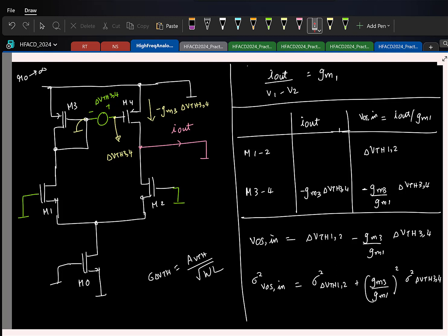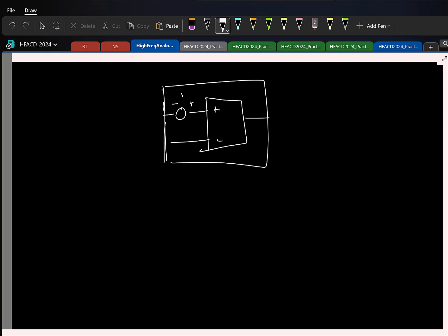Okay, so this offset voltage we will actually apply to match them after design. Oh, you mean to correct for the offset? There are different ways in which you can tackle offset actually. One is what you suggested. So let us say this is your amplifier. The offset is modeled like this. This is your final amplifier. This has an input referred offset like this, right? So to correct for it, if you can somehow add another voltage source with the opposite polarity, then effectively there is no offset. But now the point is, how do you exactly find what this is? This is one way in which you can do.